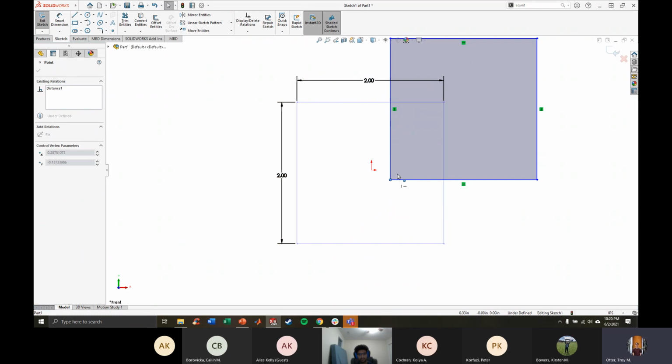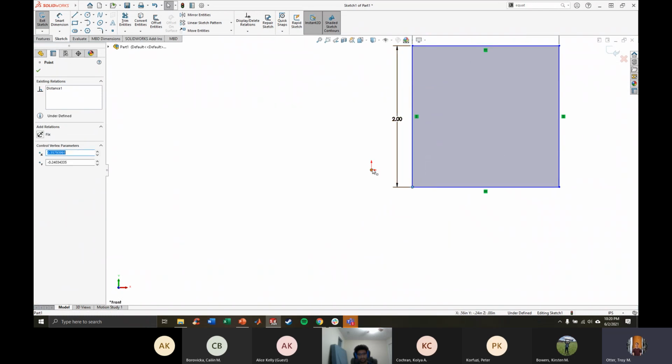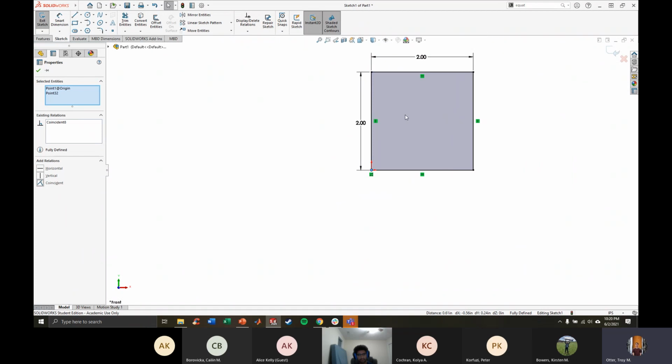The one that we're going to use right now is the coincident constraint, and we're going to put this bottom point at the origin of our part. So the origin is the place where all three of those initial top, front, and right planes meet. So to do that, we click on this bottom point, and then if you hold Control, you can multi-select points. So I have 2 points selected now, and I can make these points horizontal, vertical. If it was horizontal, these points would just be on an imaginary line. Vertical, same thing. Or I'm going to choose coincident, and that'll move these points together.